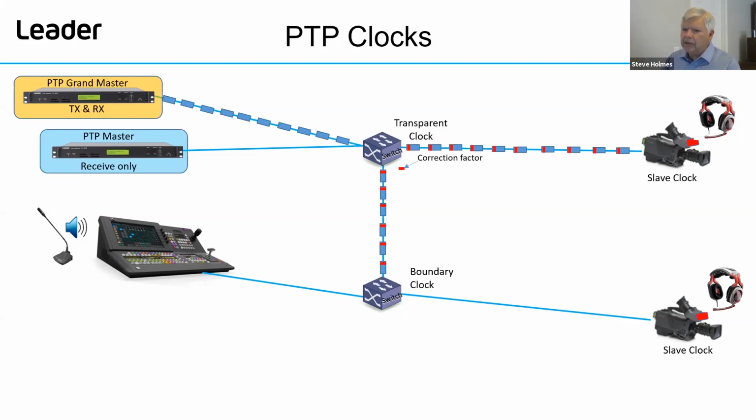And then we've got boundary clocks on the bottom, which is pretty much all that's used in today's world. The boundary clock regenerates, like I said, it's like a reclocking DA. It's going to regenerate its own brand new PTP messages on a port by port basis. It is locked to the Grandmaster, so the Grandmaster's time and the Grandmaster's announce messages will pass through the system.